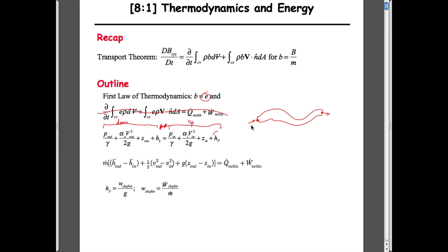So this is V, well, we've always called it 1. V upstream is 1, and downstream is 2, and they're streamline velocities. And so we just need to be cognizant of the fact that we're writing between those locations. So in this equation it's shown as in and out. The velocities are streamline velocities. They're not in or out. They're just always positive, and so we never worry about this alpha term, which you always take as 1.